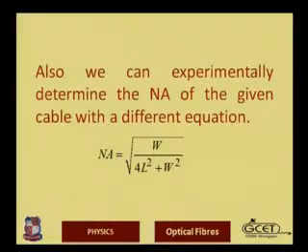Here is a fiber optic cable, and we will see it after some time, but you can see the light intensity gathering from this LED source, right? I am just showing you the initial LED, which I am now launching into this cable, and you can see the light intensity at the other end of the cable. This is done with total internal reflection. Now I'll demonstrate how we can find out the numerical aperture of this fiber optics cable. Okay, now we will move to the other table.